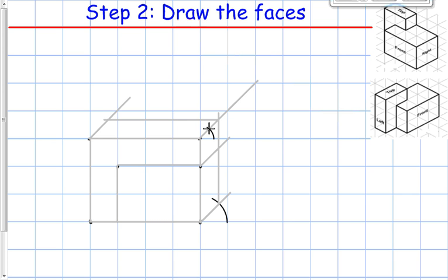So right where those two meet, I'm going to come across here. And additionally, I know that this part goes 1, 2 for the width. So I'm going to go here. I'm going to go diagonal. And we're going to start to clean this up with some object lines. So we're going to switch to object. We're going to construct our 3 faces. Face 1 is going to be these lines.